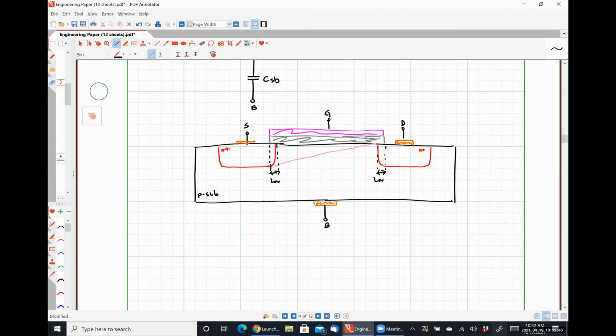When the substrate is annealed, which is a heating up process, that causes the source and drain to diffuse out a little bit, meaning that the gate will always slightly overlap the source and always slightly overlap the drain, which is why modern transistor technology has the yield that it does.